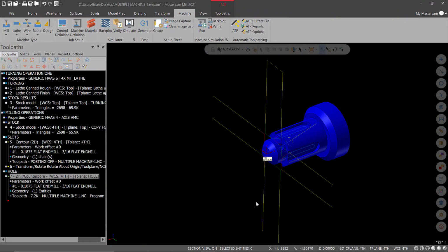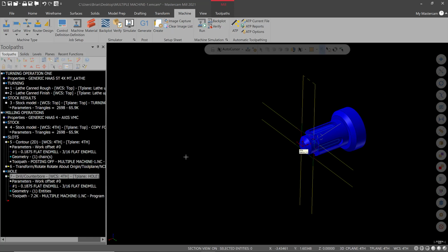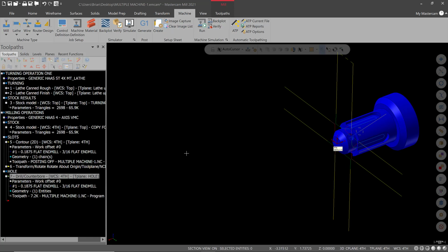All right, one thing I wanted to add to this, and you don't have to do this for the assignment, you could leave it just as we did before, is what if you go to the machine and the fourth axis is not in the X negative direction, it's on the right-hand side of the table, as they normally are. But that's not always true, but let's say I know here they are on the right for the most part when they come installed, or when you walk into the shop and they're installed.